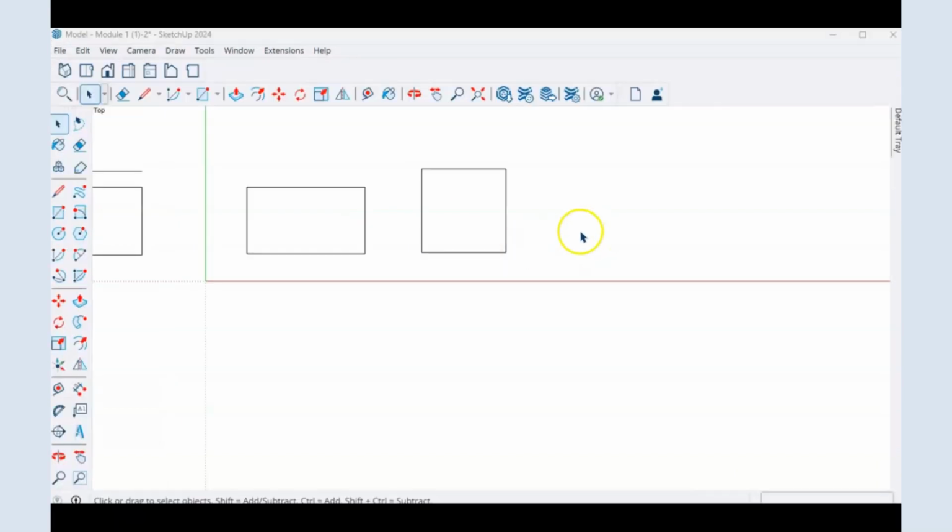Okay, so in this next example, I'm going to grab my rectangle tool, and let's say you drew a rectangle and for some reason you drew it the wrong size. I've placed my rectangle. If I just drive it with some dimensions, so 4,000, 4,000, I don't have to put in mm because that's the template I'm using.